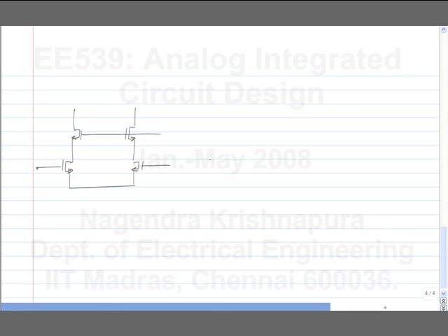So, I have drawn only the lower half of the circuit. Now, looking up here, I have a resistance of 1 over GM1. This is because here it is a low resistance, and here also it goes into a diode connected type of transistor, so here also it's a low resistance. So, looking here, I only have 1 over GM1. Looking down here, I have to analyze this circuit.